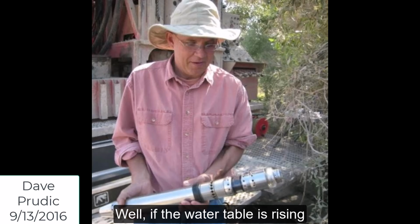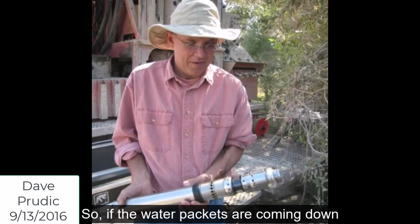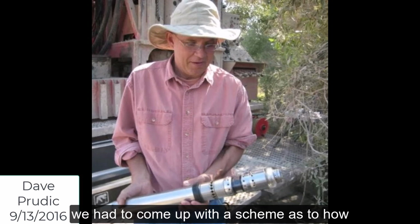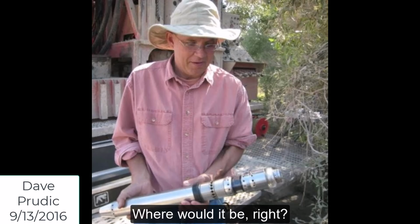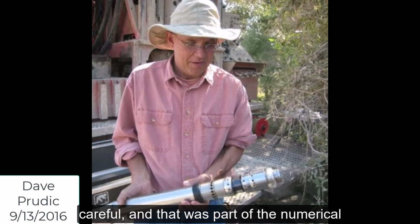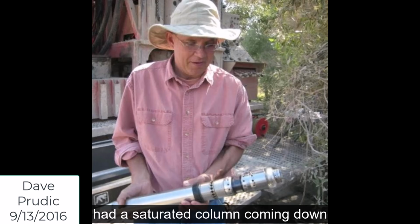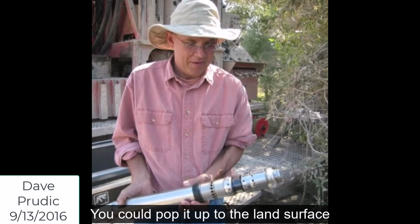Well, the water table's rising and this stuff is coming down. How do you incorporate that, right? So the water packets are coming down and the groundwater levels are coming up. We had to come up with a scheme as to how to capture that water that was coming down. Where would it be, right? So that was the big thing. And what happens if you're not careful, and that was part of the numerical instabilities, was that you essentially had a saturated column coming all the way down in UZF, right? And this groundwater table is rising and it hits that saturated zone. You could pop it up to land surface in a hurry.